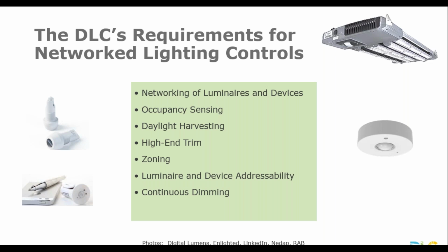The results that we found apply to any control systems that share these basic functions. For instance, luminaire level lighting controls are one type of product that provides these 7 functions. Some of the products in this report used luminaire level lighting controls with sensors and controls at every fixture. Other products used controls at every fixture for device addressability, plus a sensor for each room or zone, rather than inside every fixture. By the way, we'll see later on in the results, some of these functions like occupancy sensing were not necessarily activated in every building, even though the control systems were all capable of the functions.